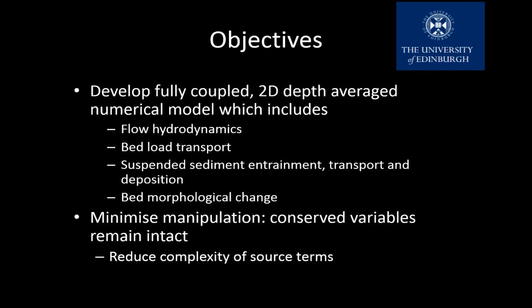One of the things is that a lot of the models are decoupled, so they update the hydrodynamics, and then they take it that the bed changes happen at a slower rate, so they decouple the problem. And other models either look at just bedload transport, when the particles are large or the flows are less intense, or they look at just suspended sediment transport, when the particles are entrained into suspension.